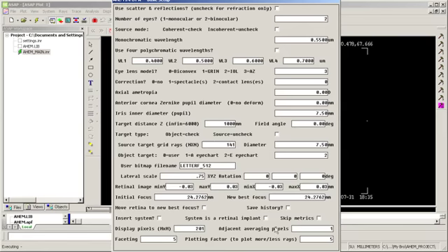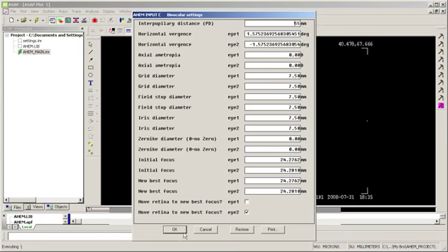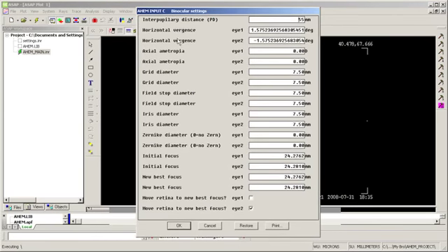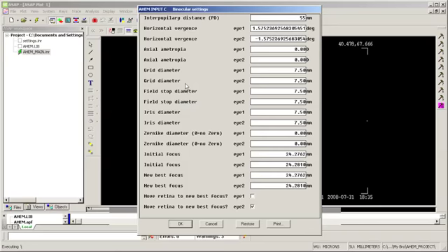So here's my retinal image window. I've got faceting of 5 and some typical setup features. Click OK. Now I get a new window of binocular settings, and I get a setting for interpupillary distance. So that's the separation distance between the center of the pupil of both eyes. Different people have their eyes separated different distances, so 55 is a fairly average number.